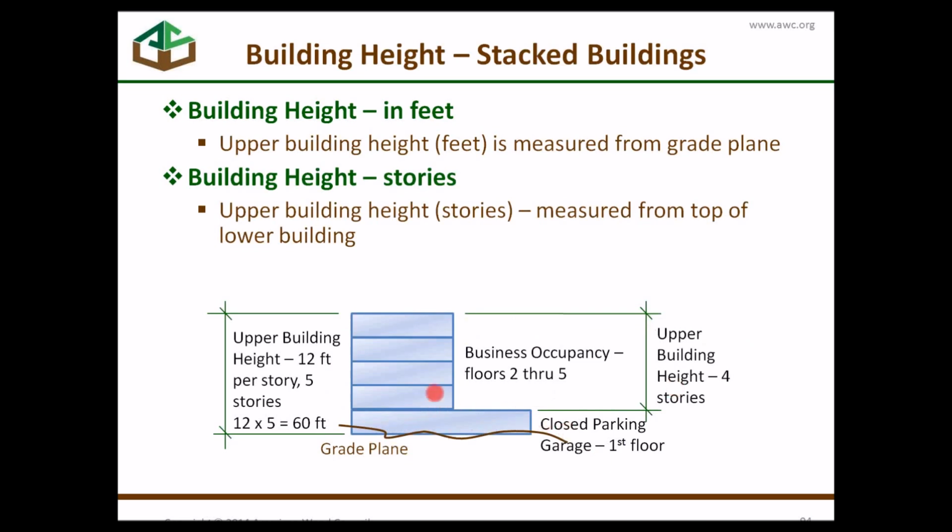It's no longer just parking down here. The distinction here, which makes it a little bit different in terms of height limits, is you get to measure the height in stories above the horizontal separation. So you start measuring the height in stories from the top of the building below. However, you're still limited in the number of feet from grade as measured from grade for this upper building.